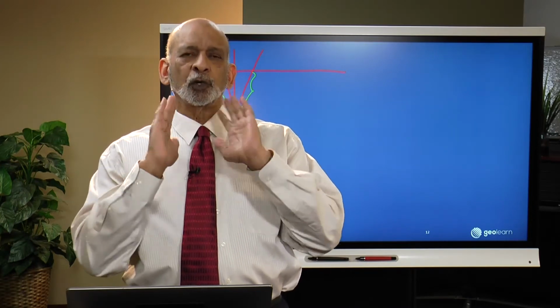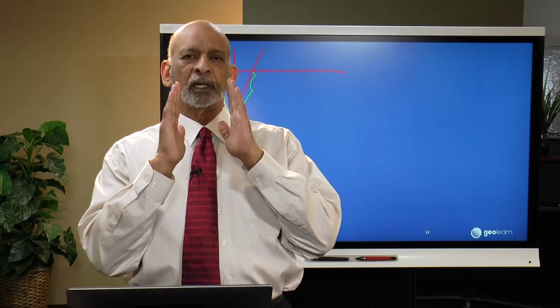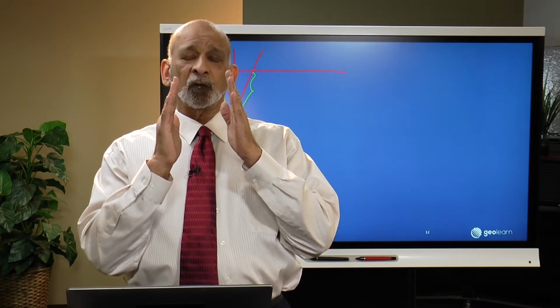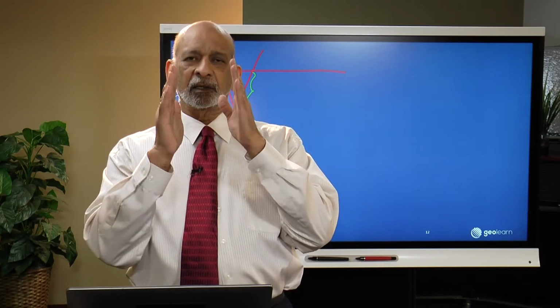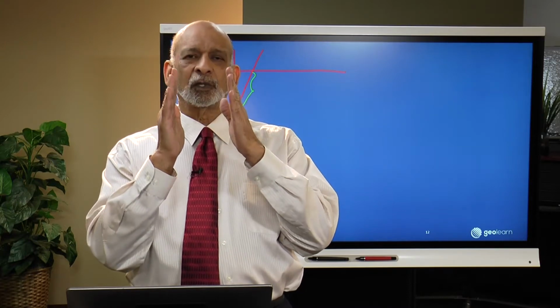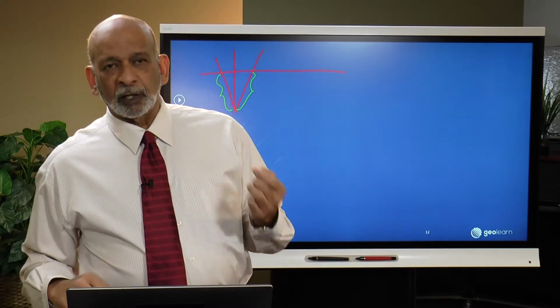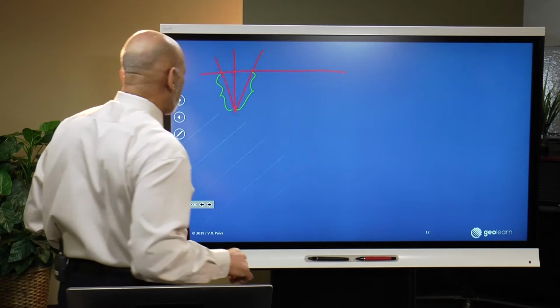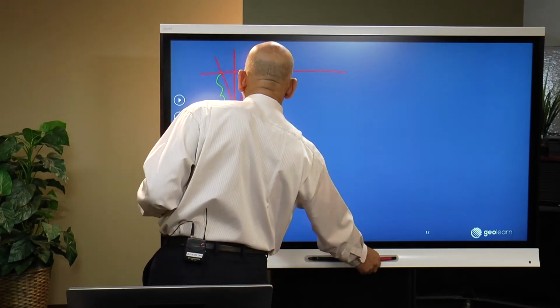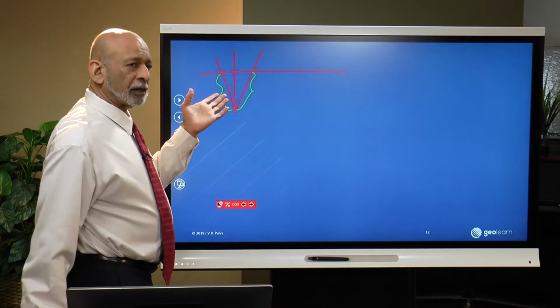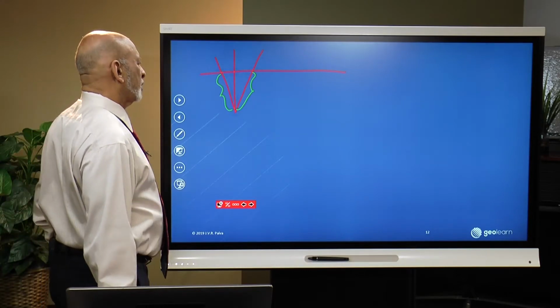Now when you wave the rod, you don't do it fast, you do it very slowly, and try to make sure that you're not going through an exaggerated arc. You only want to pass through the true vertical, so that the instrument person can observe what the lowest value on the rod is and use that number. So that's a very common thing that happens.